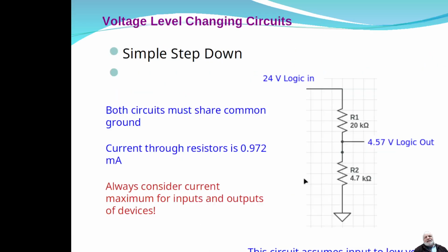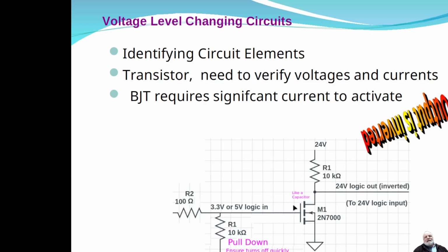If we go back and look at most of these other circuits, I didn't mention that, but this is a DC type of setup. Of course, it's just logic 0 to 1, so that's basically DC. With this type of circuit with the transistor, whether you're controlling a physical output over here, or you are trying to communicate between 2 different controllers, either way, it's just DC. You're not going to have current flowing in the opposite direction. Current only flows through one direction here.